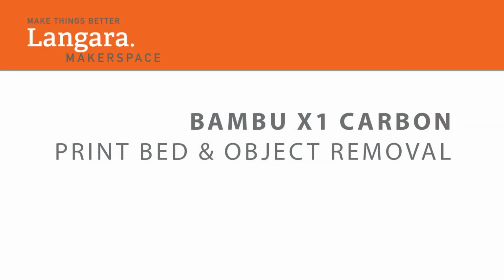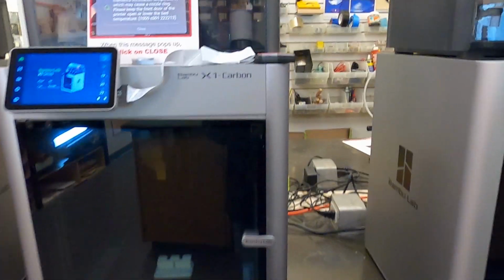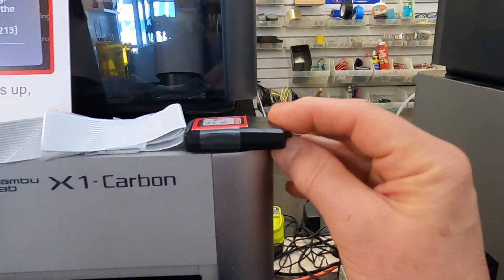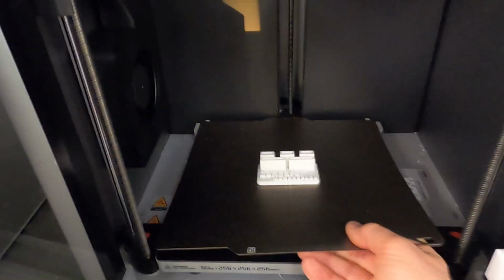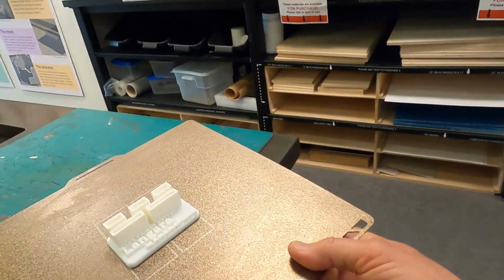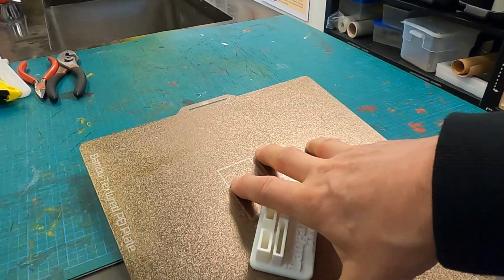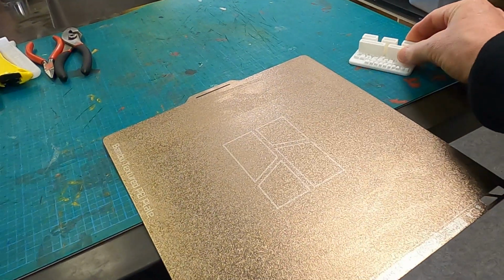So we're going to look at when your object is finished printing now. We're going to actually first turn off the printer, then eject your SD card, put it back where you found it, and just going to lift the front of the plate. It's magnetic and it should just pop out quite easily. And we're just going to kind of arc the plate to pop your print off. It might just pop out without it, but you can arc the plate and it pops off pretty easily.